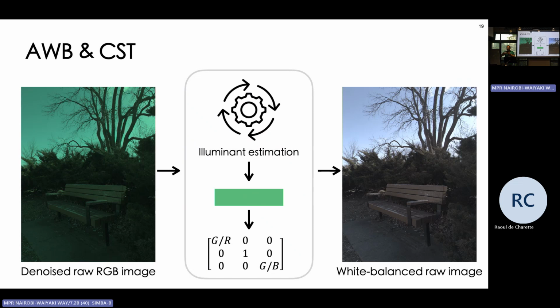Yeah. Like the goal, by definition, we try to remove this, and some users will hit that. Usually in production, in industry, we don't follow the academic definition. The academic definition tries to remove any color, but in industry we try to just remove the light color in outdoor scenes, but keep a little bit in indoor. That's why when you take any photo indoors, you can see this kind of yellowish light color still in the image, right? But if you run an algorithm from academia, it will just make it white. So just remove it, right? Yeah. So these are the two steps of auto white balance correction.